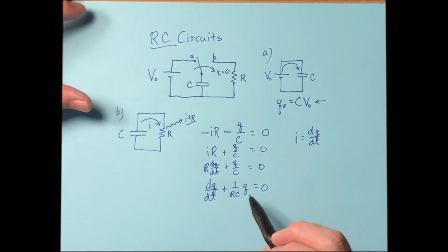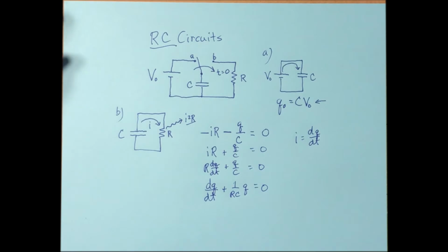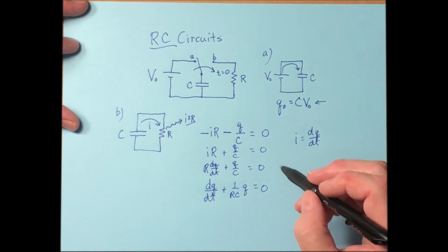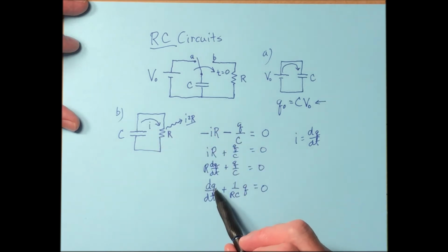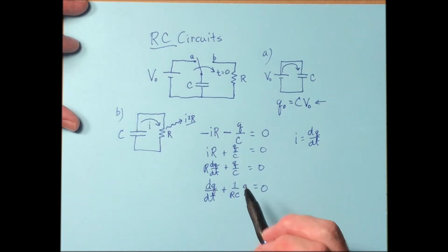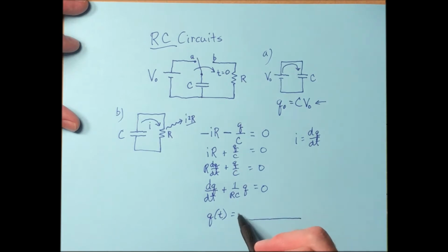But I want you to think about what this equation is. This is called an equation of state. And what it's describing here is the discharging behavior of the capacitor. The solution for this is going to be some Q that is a function of time. Now, there's going to be a function over here on the right-hand side that's going to have a t in it somewhere. So that's what I mean. Q is a function of time.